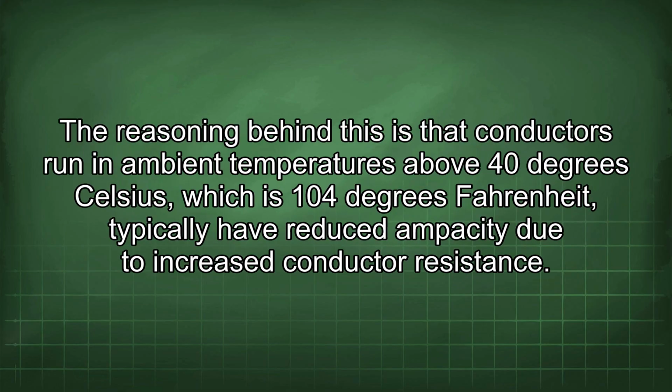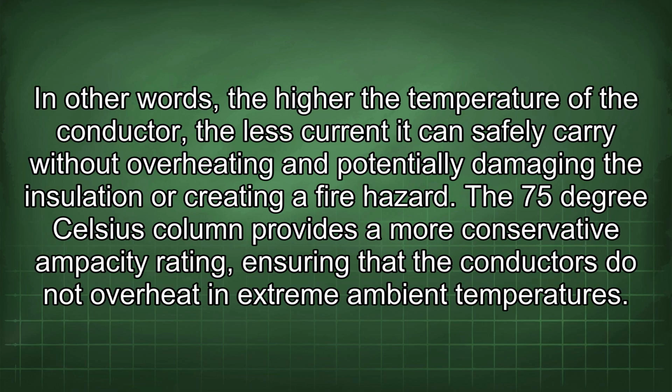The reasoning behind this is that conductors run in ambient temperatures above 40°C, which is 104°F, typically have reduced ampacity due to increased conductor resistance. In other words, the higher the temperature of the conductor, the less current it can safely carry without overheating and potentially damaging the insulation or creating a fire hazard.